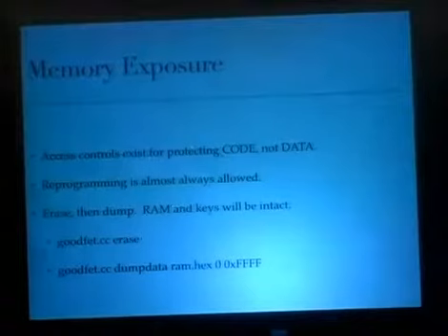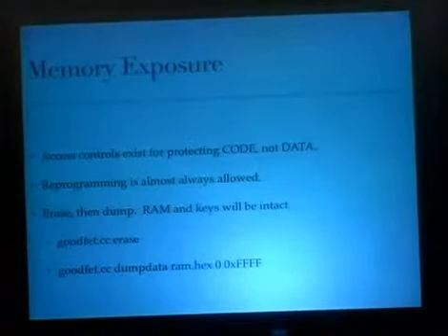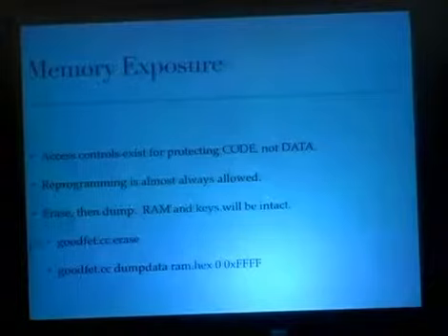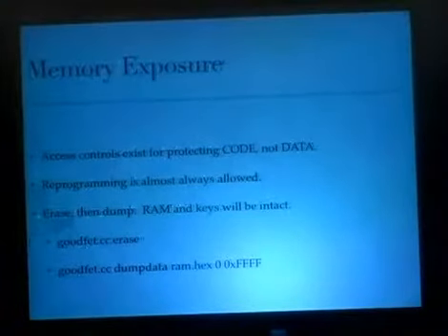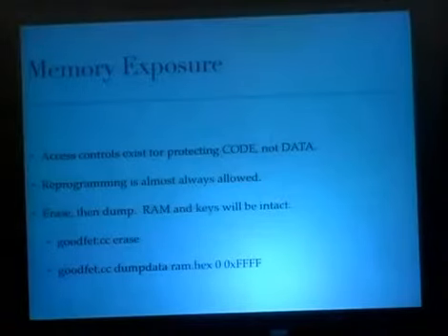If you want to get a copy of all of the memory of the Girltech IMME that's in RAM, that is every key, every global variable, all of the radio configuration registers, all of that stuff, you just run these two commands from your GoodFET. You do goodfet.chipcon erase, and then goodfet.chipcon dump datafilename from 0 to the end. And you get this nice little image.